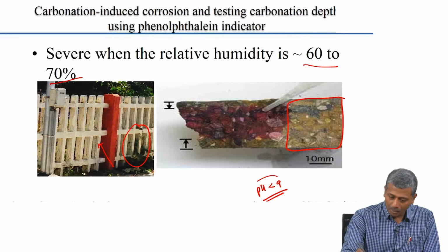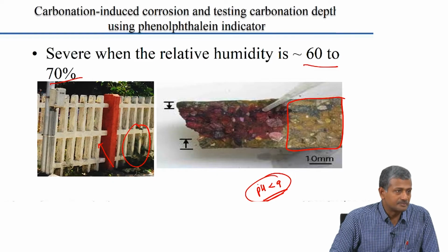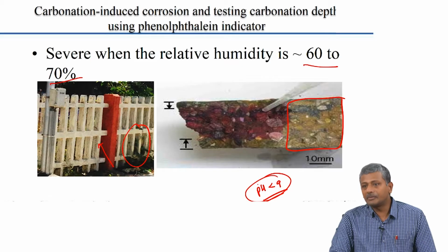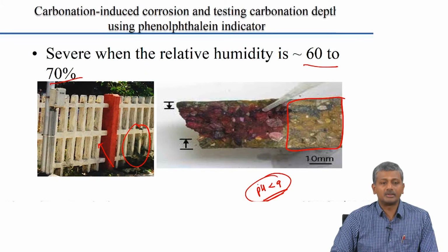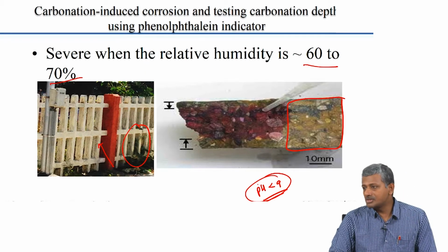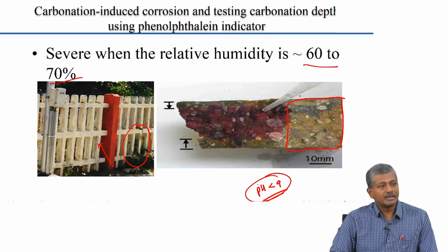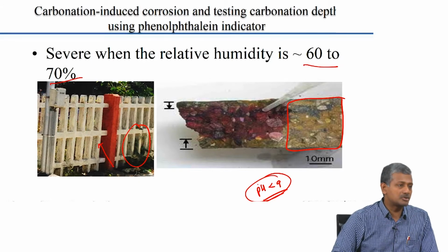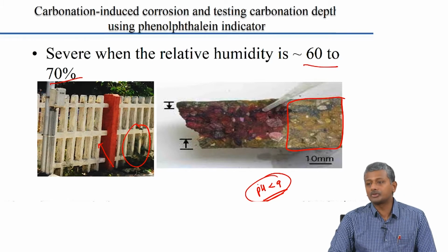Now, this is often a problem in detecting the critical level of carbonation that has happened in a system. If you use the phenolphthalein test, the discoloration will happen only when the pH crosses the barrier of 9, but most researchers tend to believe that that is already a little bit too late. When your pH is reaching less than 11 itself, the stable passive film around the steel has already started deteriorating. So, there has to be other means to understand the depth of the carbonation front without really relying too much on the phenolphthalein test.